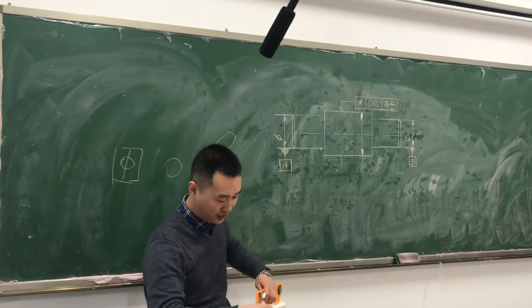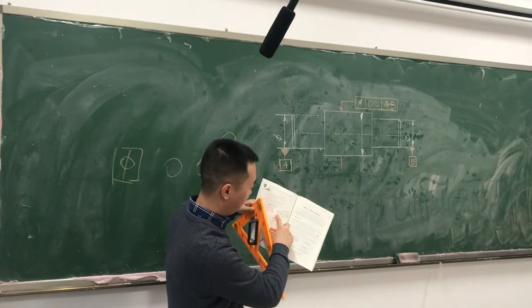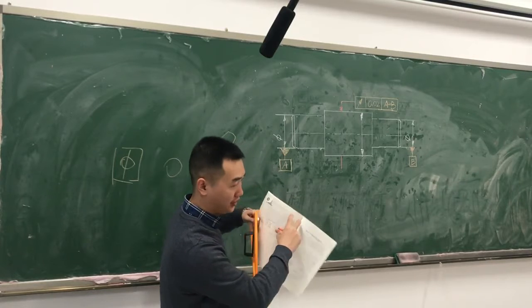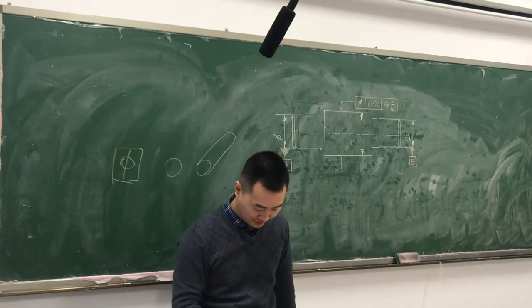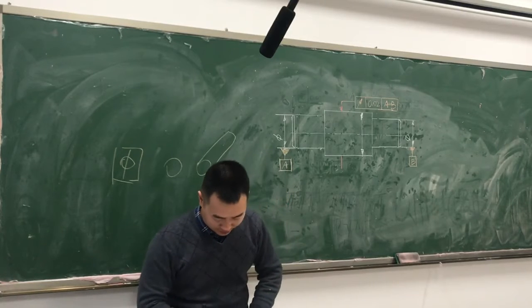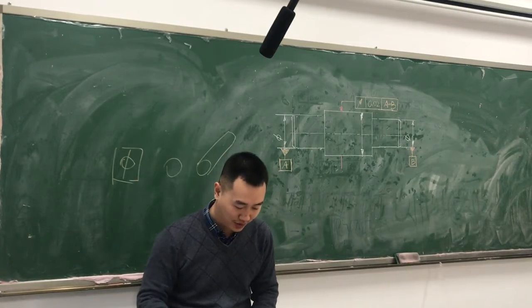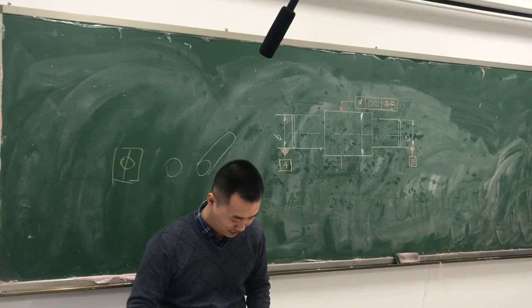And here we got the value first, tolerance frame 0.02, and this characteristic. So is there anything wrong with it? If you are not sure what the characteristic means, you should find it on page 19.2.